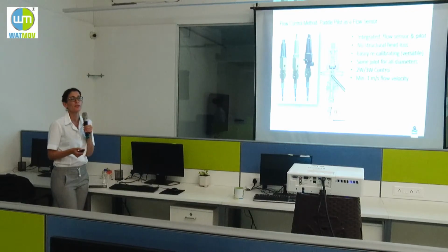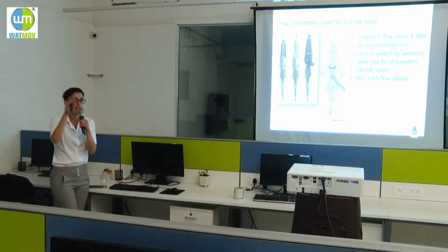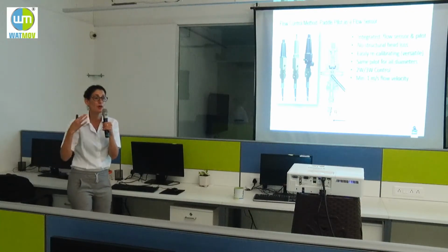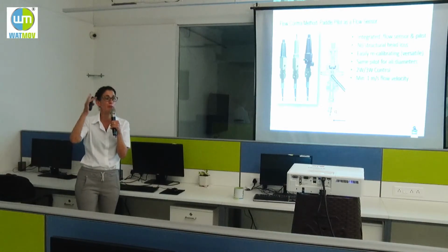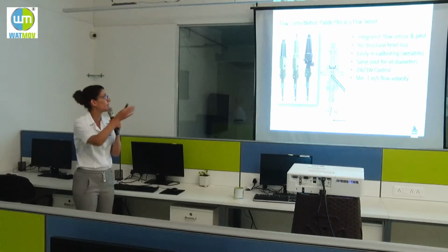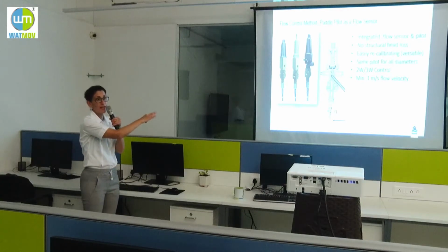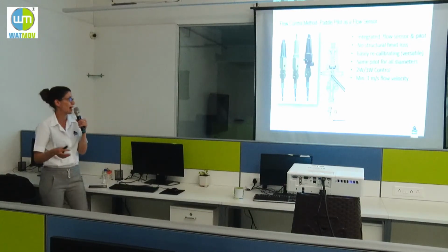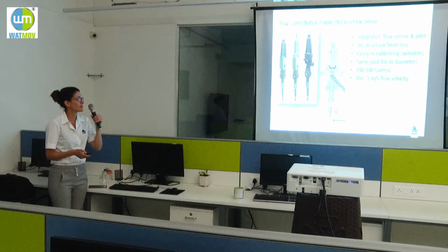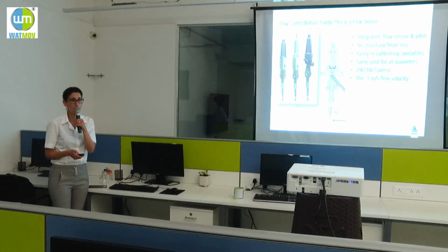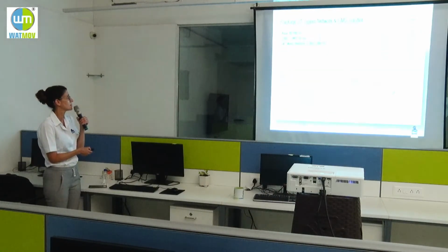And also, when we talk about orifice, we have the sensor of the flow, which is the orifice, and we have the pilot, the differential pilot. Here, it's only one integrated unit of sensor and pilot. And as I said, it's easy to recalibrate and change the calibration at the site.